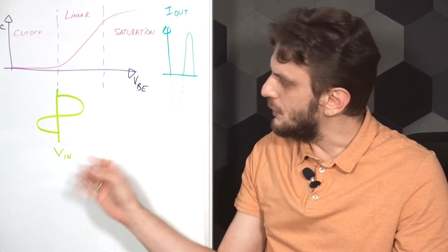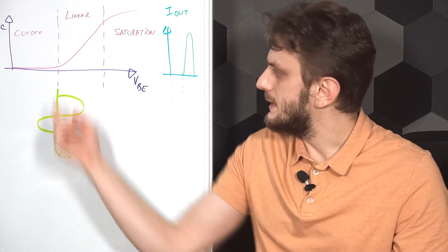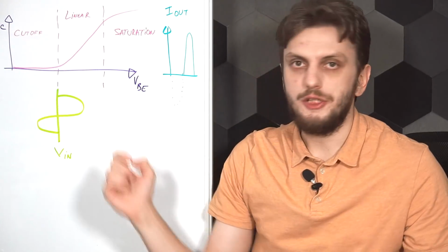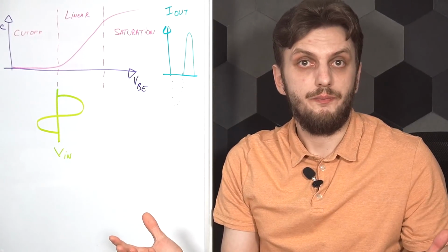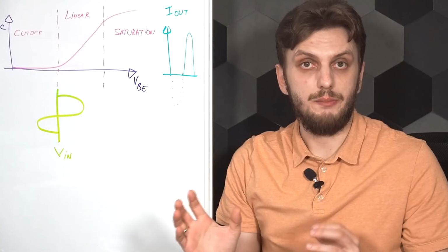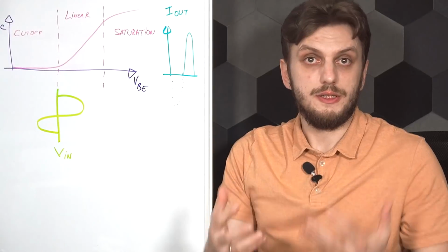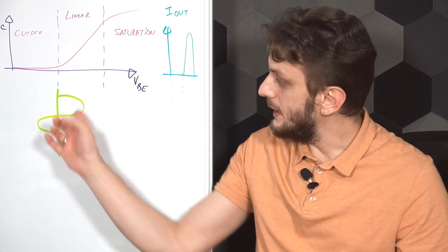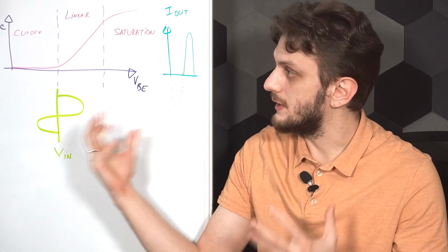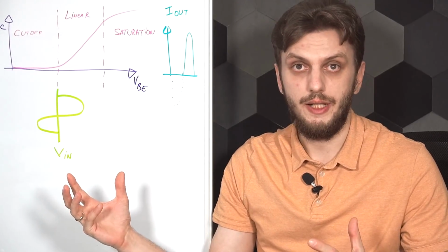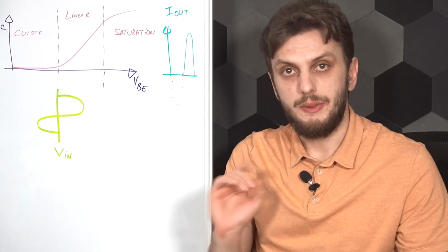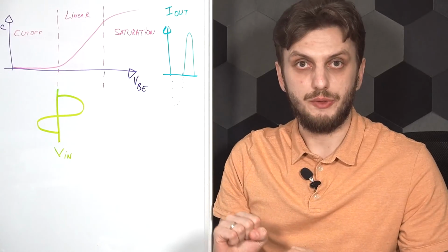So only half of the signal passes through the amplifier and gets amplified. Now, the main advantage of doing things this way is that the static operating point is in a region where there's no collector current. So the standby current of the amplifier can be made to be extremely small. Current consumption only increases when there is an input signal. And this current consumption isn't just dependent on the presence of an input signal, but it's dependent on the amplitude of the input signal.